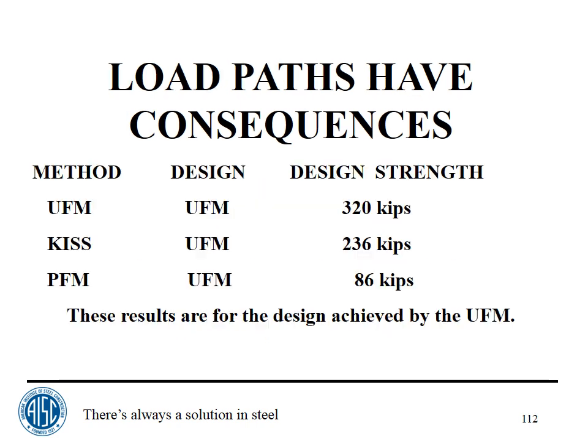So you can see the same thing is happening here as in the 3-bar structure. I think the uniform force method is closest to the true solution, closest to satisfying all 3 principles of engineering mechanics. And of the other 2, KISS is actually better in this case than the parallel force method. But if I went to a column flange, I think you'd find the parallel force method is better than the KISS method.